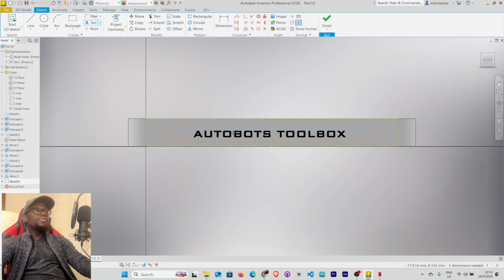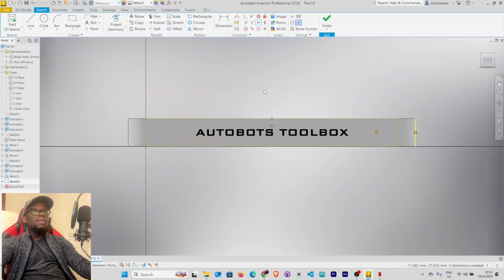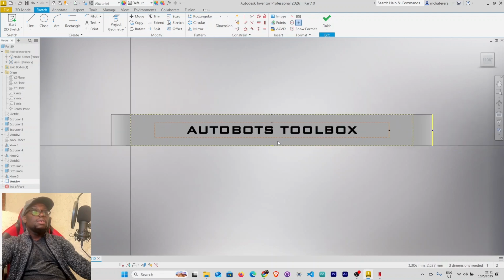So there you go. And then let's select our vertical constraint, center of our text, and the center here. They have to be aligned. Horizontal constraint, this and this. Right click OK. The dimensions are needed. What are those? Auto dimension. Apply.